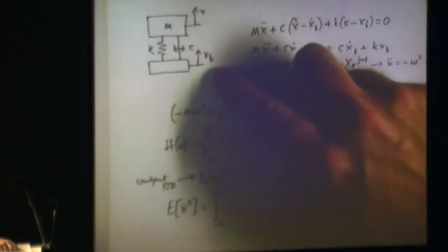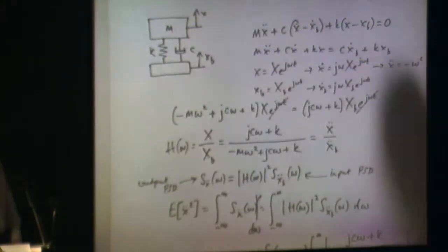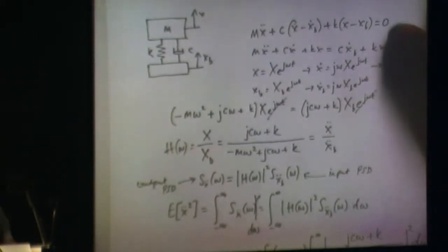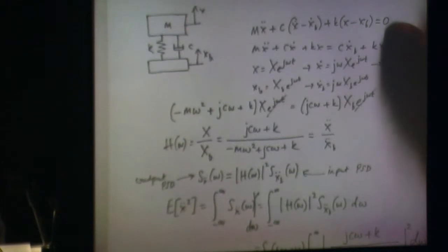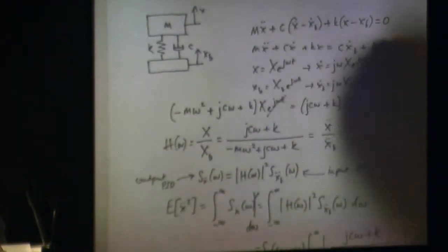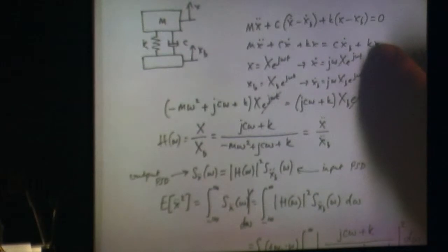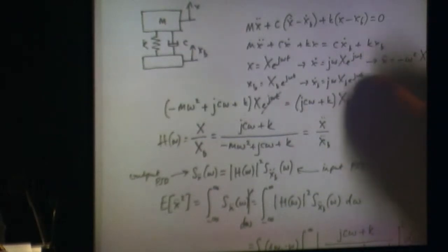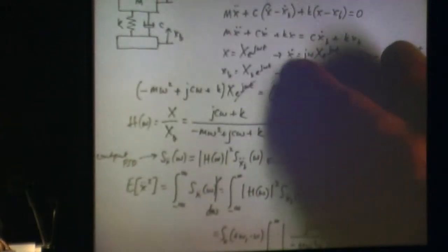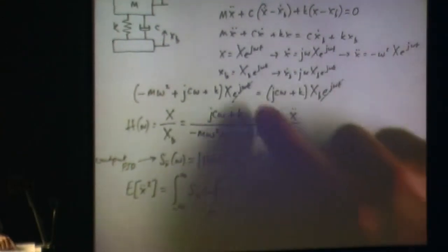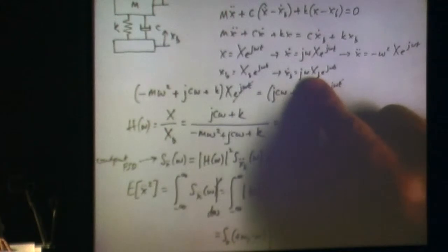It's a mass, so a base excitation problem. So the equation of motion looks like this. If I took the free body diagram of m, my mass, then this is what I get. I put all the x terms on one side and the x b terms on the other side, over here. Make the substitution with an oscillation, so my exponential terms. So I get my x dot, my x double dot, and the same with xb, I get my xb dot.